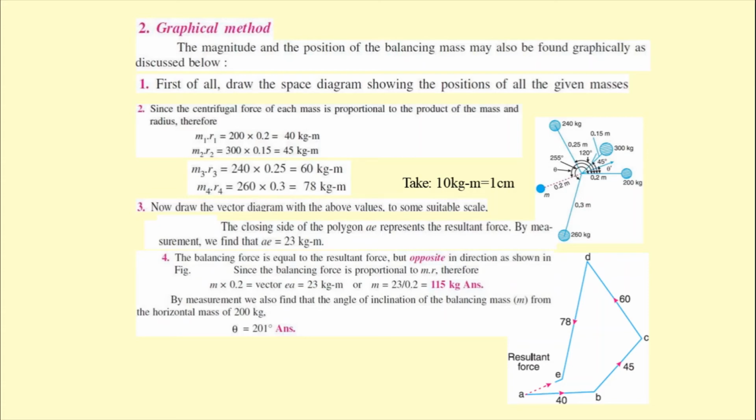So with respect to that, if we take the angular position of this particular line B to A to E dash, where E dash is the position which lies along the same line, with AE equal to AE dash, and AE dash is 180 degree apart from AE, then the angle that we are going to get is 201 degree. So thus we can find it out. Try it.